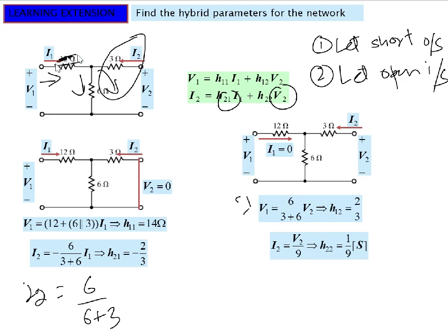We will not talk about this 12. Why? Because we are talking about current, not voltage drops. So current is here, and I want a part of this current which is in this branch. So that is actually opposite to our current I1. So minus would be used either with this side or with this. We will use it with this side, and then we will multiply our current I1 and write the branch in which it is not flowing. So this is the current divider rule.